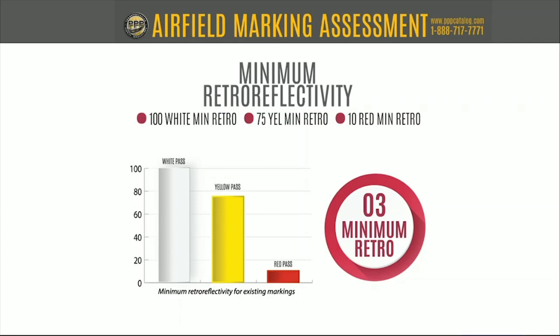The average on the entire airfield was like 690 millicandela, or 640, something like that, white and yellow combined. That was with high index beads, so you will get a difference there, and you've heard us talk a lot about that already.